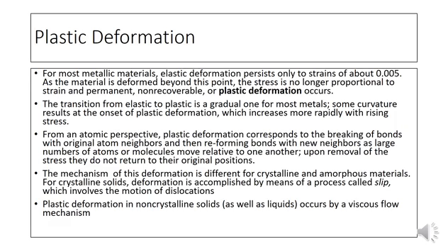And at a molecular level, for crystalline materials, when we get to plastic deformation, the atoms are breaking and forming new bonds with the neighboring atoms, and once the force is removed, they no longer return to the original positions. But for non-crystalline materials, the bonds are breaking and the material starts flowing, and if the force is continually applied, the material will flow.